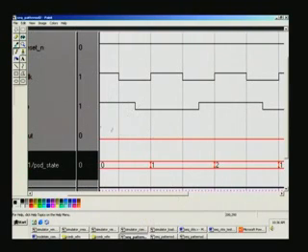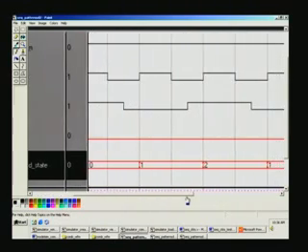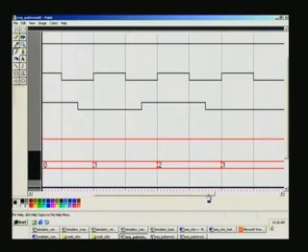Here the actual input is applied with a little offset, because when we come to the positive edge of the clock, it must see a stable value at the input. That is why we have taken care in the test bench which we have seen earlier. And now you can see this bit pattern that's being applied from the test bench.